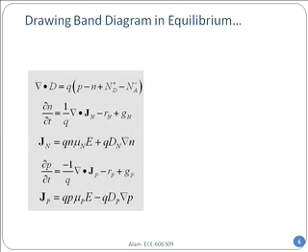That means in equilibrium, there is this detail balance. Equilibrium doesn't mean that nothing is happening. Yes, the diode is sitting on your desk, doing nothing. But internally, a violent storm is raging. Electrons jumping to the conduction band, electrons coming from the conduction band to the valence band, electrons going back and forth between one side of the junction and the other side of the junction. Huge electric field inside the device. But from outside, everything looks calm, no current coming out. And if there is no current coming out, then we will not worry about the continuity equations and the associated.